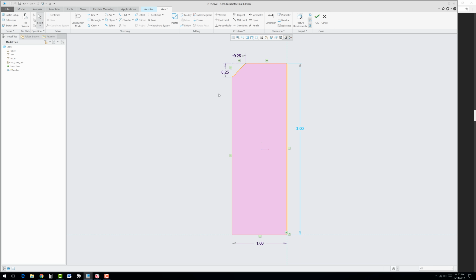The next thing we're going to do is select the circle tool. Now you could use some of the other arcs and things like that, but I want to go over the trim tool again. And here, just slightly to the right of that line on the left, take careful note where my pointer is, click, and drag out a circle that intersects past the left line. Click again and middle click, and it should bring up the dimensions. You'll see this dimension is a weak dimension, so you could actually click on that and lock it if you like.